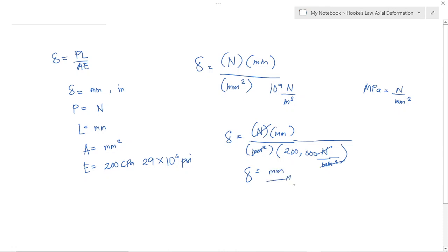Okay, so again, to make it simple, P in Newton, length in millimeter, area in square millimeter, E in megapascal. Gagawin nyo lang times 1,000 para maging megapascal. Yung 200 gigapascal, that is equivalent to 200,000 megapascal. Substitute nyo lang dito sa E.